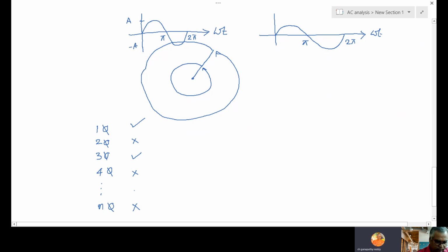For light load below 3 HP, single phase is sufficient. For more than 3 HP, three phase supply is necessary. If the load is less, single phase is sufficient to rotate the rotor. If it is a heavy load, single phase cannot rotate the rotor.